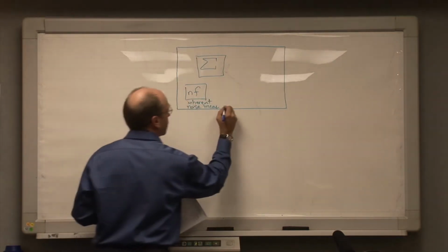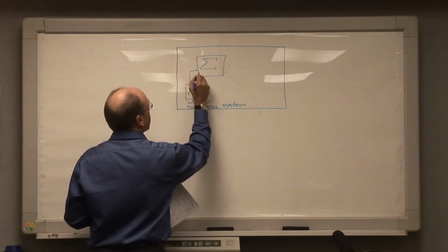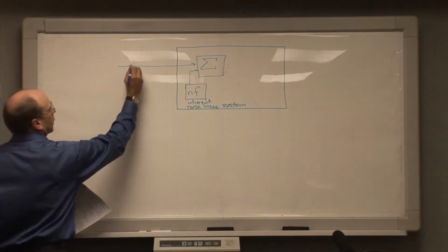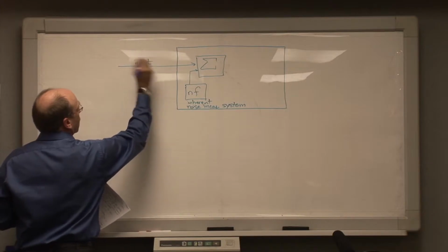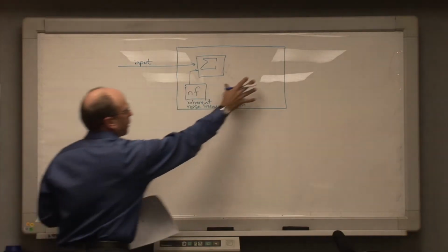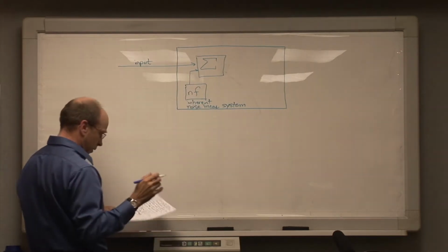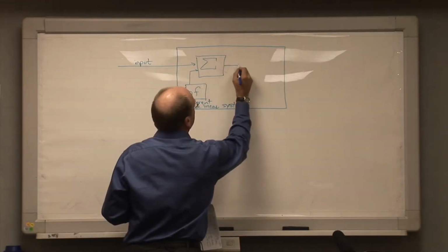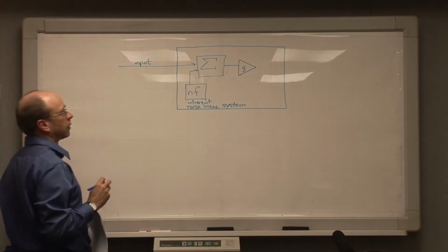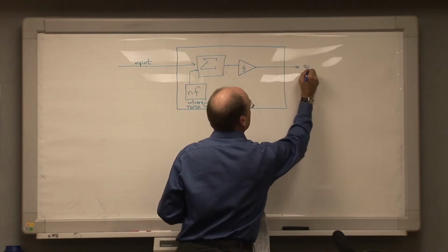We've talked about this in past talks, of course, at length. And the inherent noise generated by the measurement system is assumed to be added to whatever the input power is that's coming from the outside world. It could be coming from an antenna, it could be coming from whatever source we have, and what we want to do is calibrate this system. Having summed whatever the input is with the inherent noise generated inside the measurement system, we have an ideal noiseless gain stage that has a linear gain, G, and then we have the system output here.